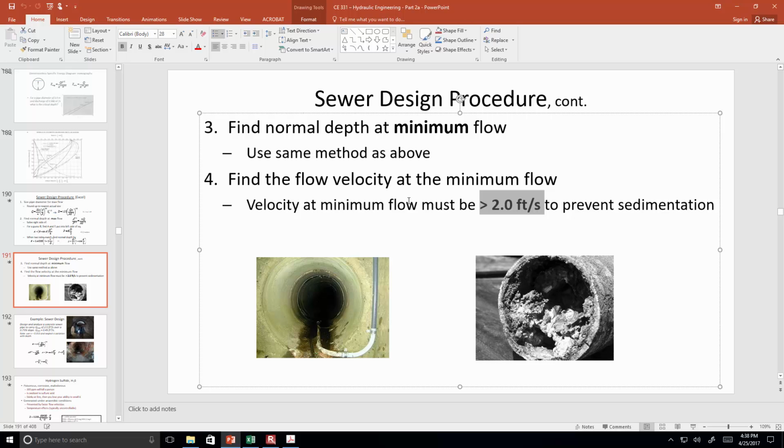If you've got just a little bit of flow and it's really close to the bottom of the pipe, you'd see that most of the flow is right in contact with the surface where the friction is being applied. And so you're going to have a really low velocity. Whereas if we had a smaller pipe, it would have been more full and the velocity would have been faster. So you want to have the pipe be large enough, but not excessively large.